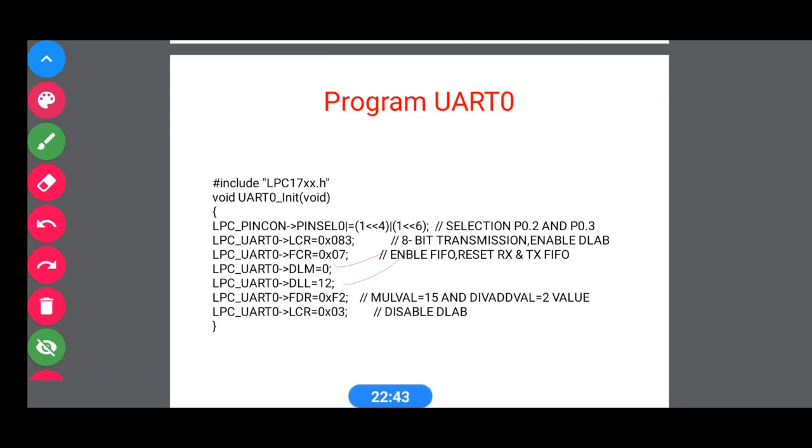Then we are loading the prescaler multiplier value and prescaler divisor value, which are 15 and 2, into the FDR register as 0xF2 in hex. After loading this divisor value, as I already told, the 7th bit of the LCR, which is the DLAB, must be enabled while loading this value. After loading this value, the DLAB must be disabled.